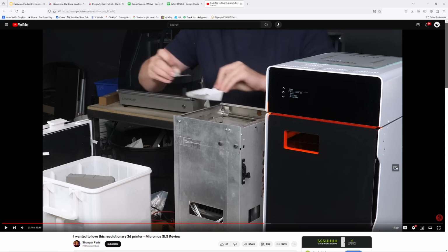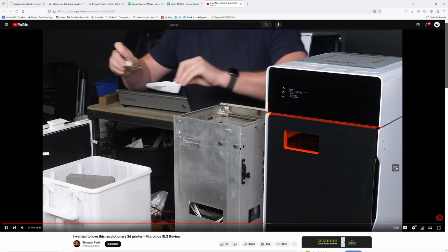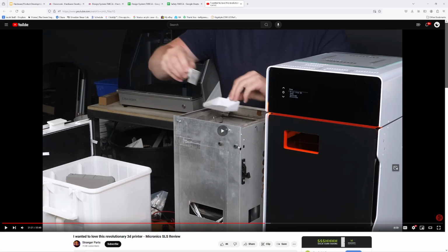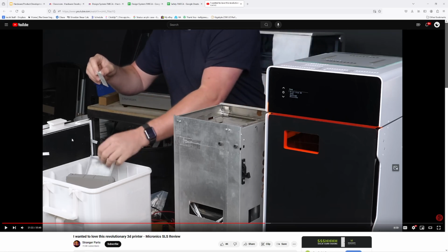So overall, for kind of a cheaper product for SLS, I mean, generally SLS printers like this are 20,000 or higher. This machine's 3,000, 4,000. Still in here. And they provide you a little scooper. Now, of course, I think there's no mounting provisions. The only mounting provisions for this guy is on this shifter. There's no mounting positions to put it back on the build base.